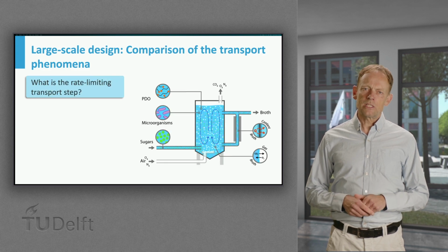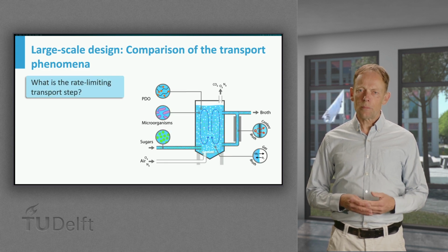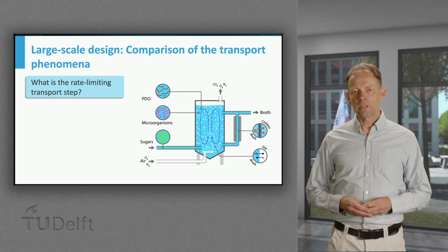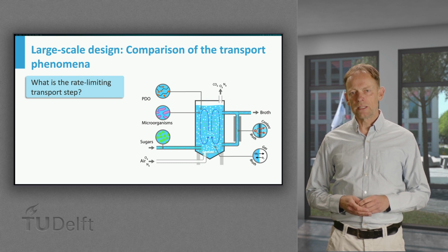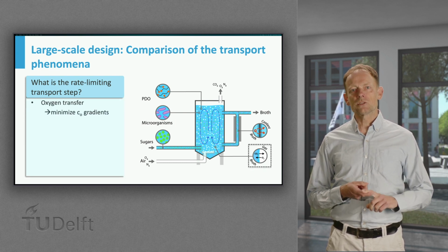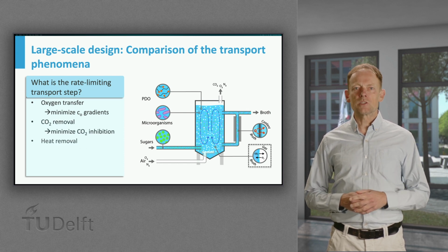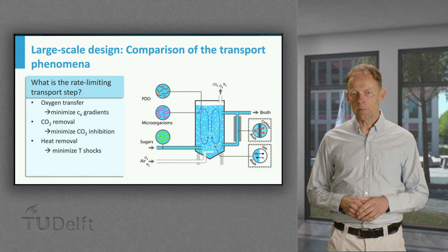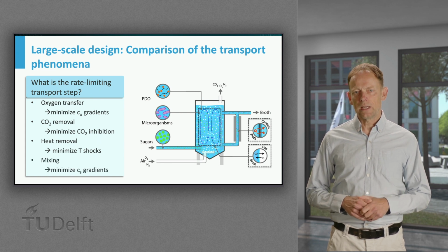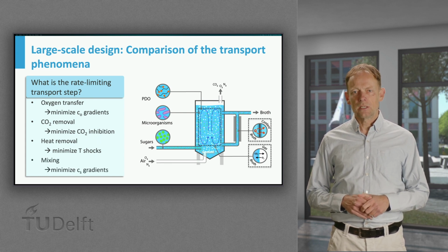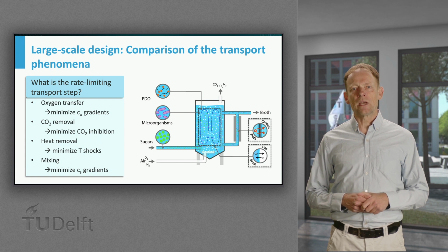When errors and mistakes are ruled out, scale-up issues in biotech processes are usually related to poor mass transfer or poor mixing, while poor heat transfer is occurring less often and can be prevented using good engineering design practice, applying enough cooling area and low cooling water temperatures.